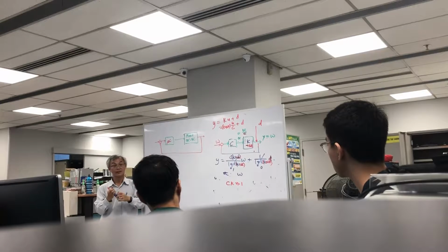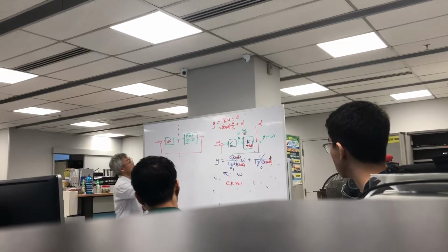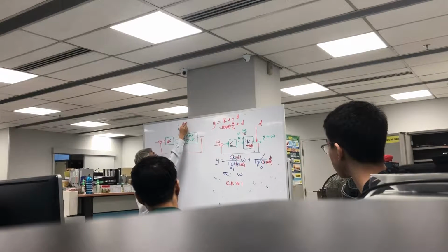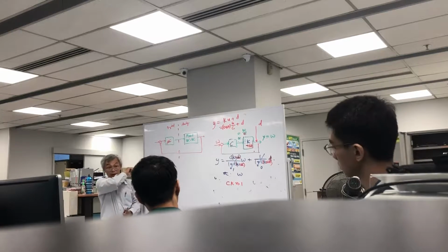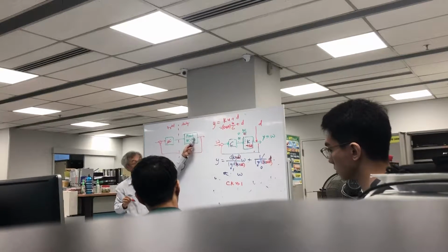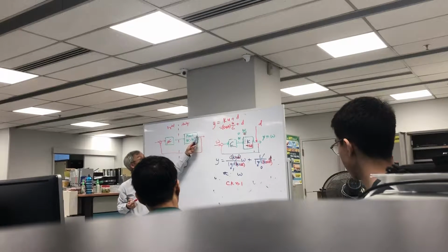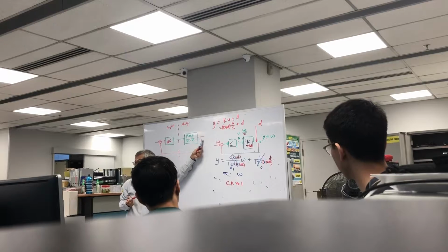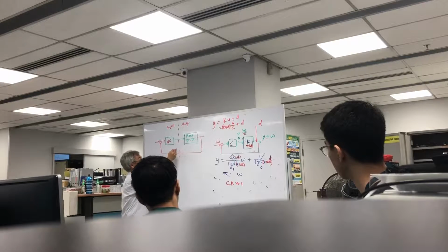You need to bring the information into the system, and usually you studied this before, right? So this is the analog world. This is the digital world. Let's take for example your DC-DC converter. What's the output? It is your voltage. How do you bring this into the microcontroller? ADC. You need an ADC. You need this component.